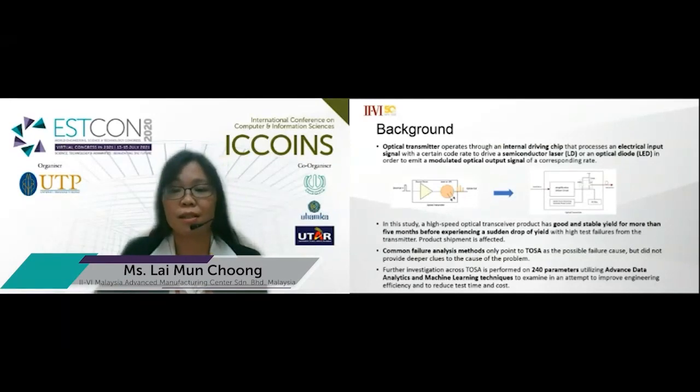So in this study, a high-speed optical transceiver product had a good and stable yield for more than 5 months before experiencing a sudden drop of yield with high test failure from the transmitter. This has affected the product shipment. Common failure analysis methods only point to TOSA as the possible failure cause, but did not provide deeper clues to the cause of the problem.